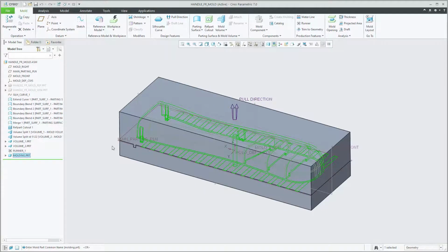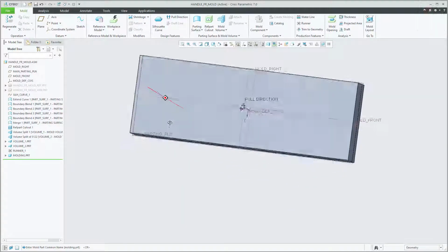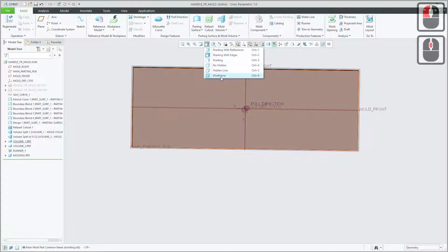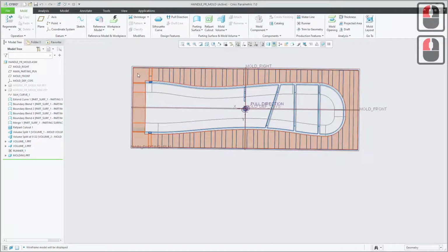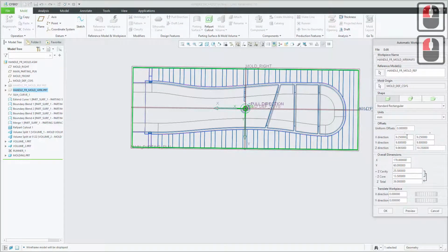Other things that you can do with these moulds, you can add clamping features into the mould. So I think in this particular setup, if we were to put features on the corners of the mould over here that maybe were through holes that ran all the way through the top section and the bottom section of the mould, then we may end up having to increase the size of the workpiece slightly. So at the moment I think we've got an approximately 10mm offset away from the finished part. It may be that we may have to increase that somewhat.